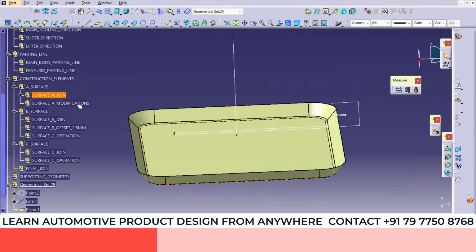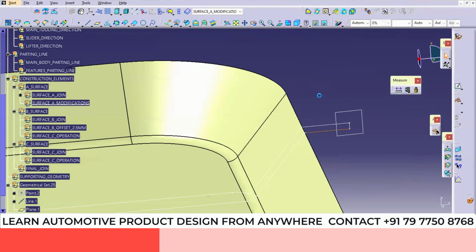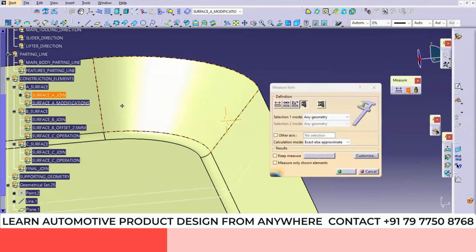First we'll create a class A surface. So in the A surface modifications, this patch we want to create, right? So for this patch, first I need a length. And when you are working on the master section, don't use the extract command. We want the parametric model. This I can extract and use, right? But that is not allowed. So you need to create it using the other commands.